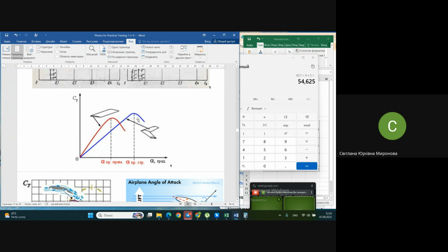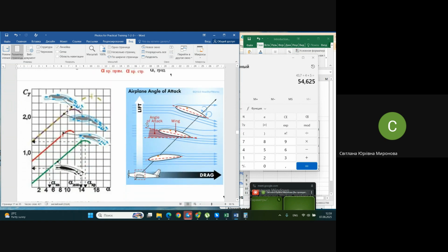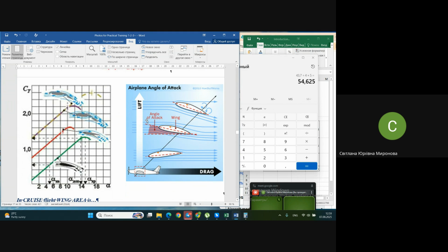What is the idea of such a wing? I hope you do remember. When we are flying already with transonic speed, the wing still flies with subsonic speed and has less drag. Next, here is practically about the same. This coefficient depends on the profile, I said. First, we may take different profiles for our airplane. And secondly, we may change the shape of the profile.